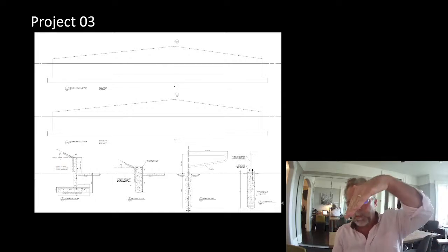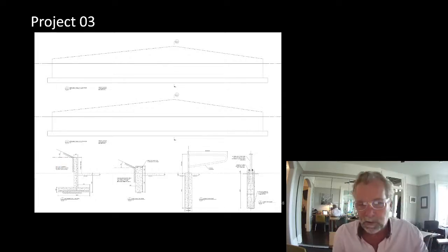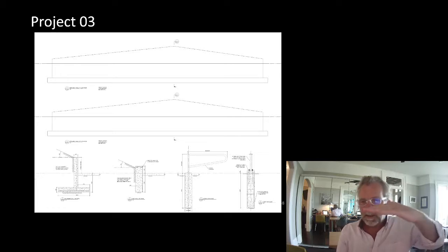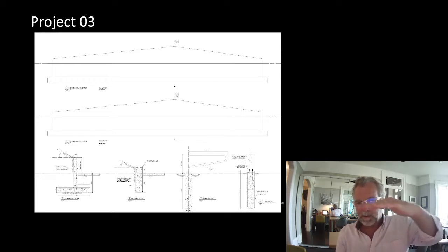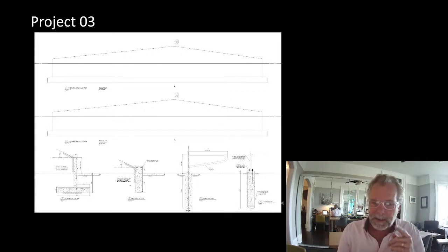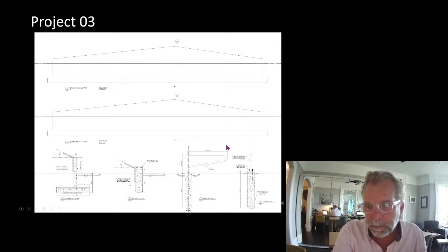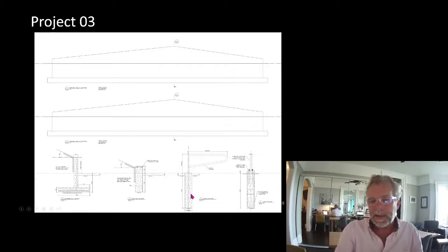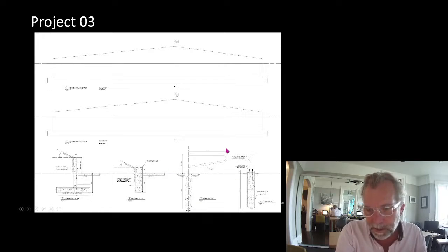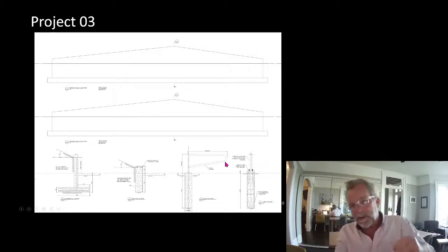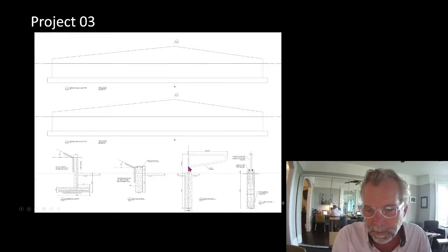The steeper the slope is, the more earth pressure there is on the wall. So typically we consider the grade at the top of the wall to be flat, but that's not a guarantee. And if it is not flat, then it affects the amount of earth pressure. There's a swing gate in this case. So the gate, we would consider one drunk guy. We put 1 kilonewton right on the tip, and that would determine the amount of overturning on our drilled pier.